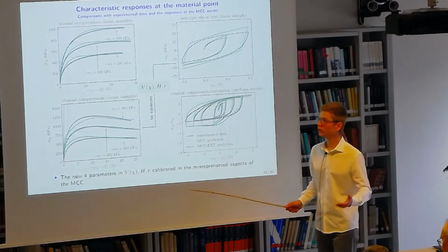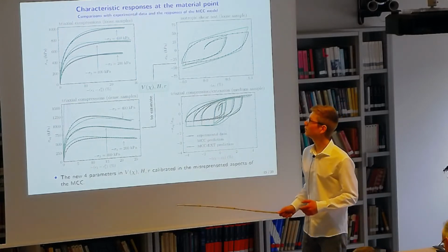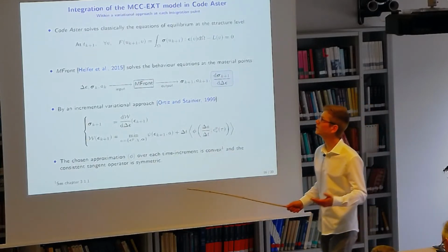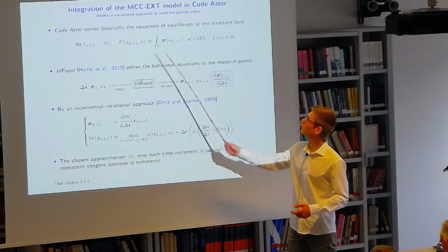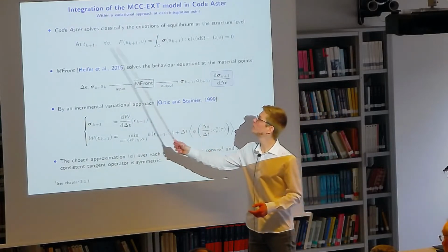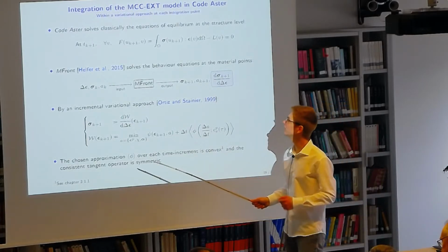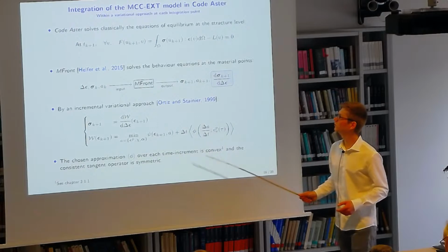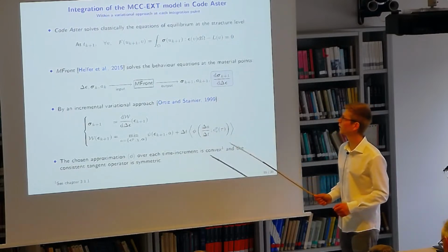However, up to now, we haven't said a word about how this model, both the MCC and its extension, can be integrated numerically and about its robustness properties. To give a few words about this and how it is used in Code_Aster at EDF, usually this finite element software is going to solve an equation of equilibrium by making zero some residual at each time step with respect to the displacement. As for the integration of the constitutive equations, they are nested at the material points and are solved by the source code generator MFront, whose role is to update the stress sigma, the internal variable A, as well as to compute a consistent tangent operator.